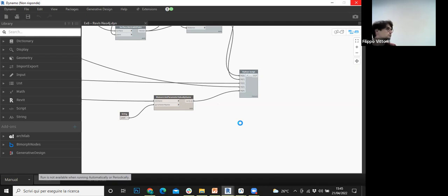So this Dynamo script is transforming this relatively complex BIM model into a more simplified manifestation of the relationships in the nodes. Is that right? Basically what he is doing now is considering all the rooms in SD4. He's deconstructing the geometry of the rooms by obtaining only the vertical surfaces. Then, starting from the barycenter of each surface, he makes 2 points, one in each direction, and uses the points to understand which room is adjacent to the other one. If you have the double condition, it matches the room and gives you the output.